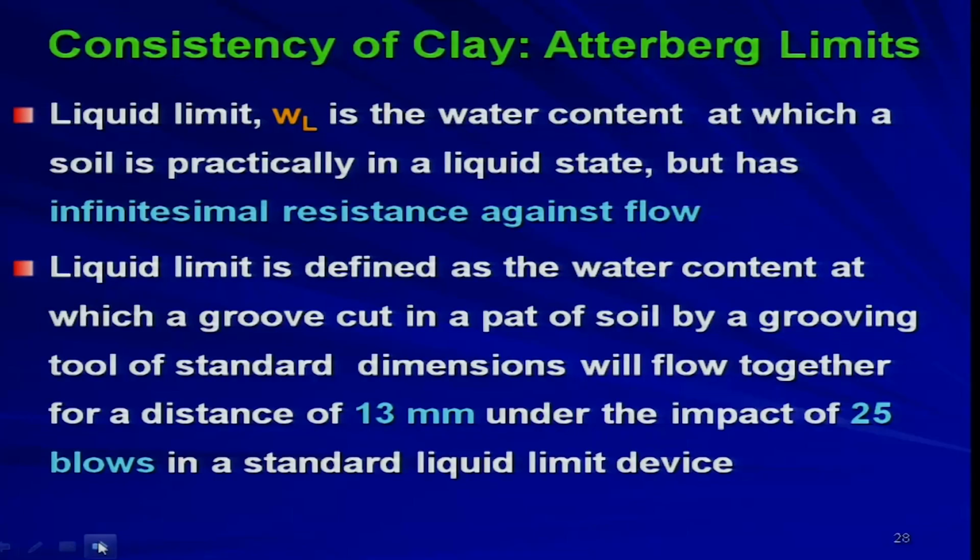Anyway, the liquid limit is defined as the water content at which a groove cut in a pad of soil by a grooving tool of standard dimensions will flow together for a distance of 13 millimeter under the impact of 25 blows in a standard liquid limit device. So, this is basically your laboratory experiment device.